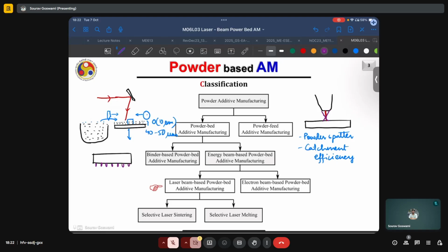Of course, it might require some post processing like a sintering step in order to achieve final product level hardness. But still, this binder will impart some minimum level of strength to the part so that we are able to handle it.